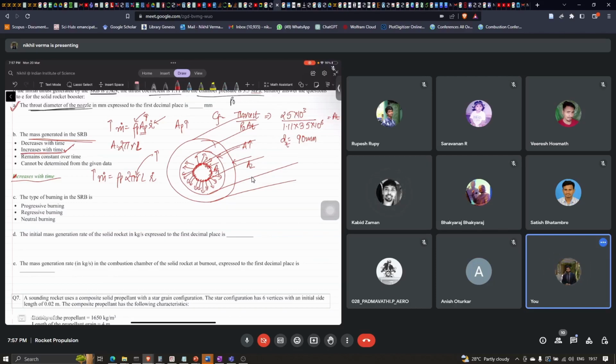I have one question related to the Pc. As the area increases, the port diameter and the volume of that port are increasing, right? Will the Pc remain constant or will it go down? It will actually increase. The Pc will also increase because, unless you change the throat diameter, the mass flow rate getting stored inside this volume will increase, and this will increase the pressure.